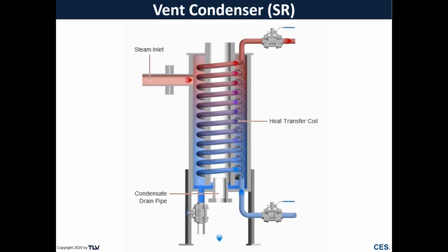At that point, the only advantage is recovering some condensate back to the system. So depending on the facility and the water needs in that facility, there's a variety of sources that may be worthwhile. It could be boiler feed water or possibly process water. But the important thing is that we have a use for this hot water.